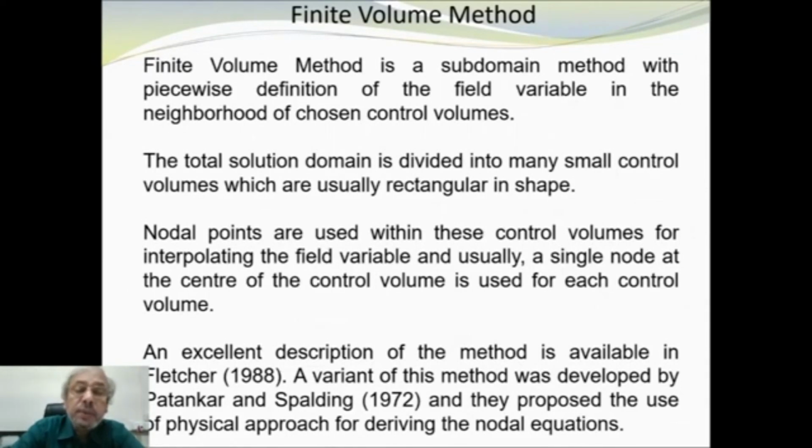It can have variation in shape. Nodal points are used within these control volumes. You can call them cells, for interpolating the field variables, and usually a single node at the center of the control volume, the center of this cell, is used for each control volume.